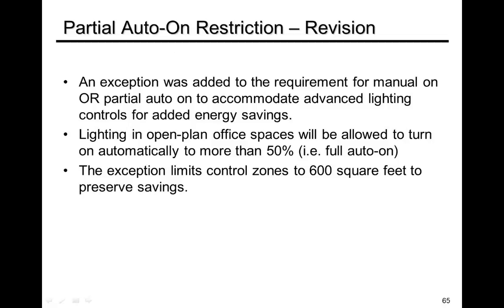The issue has been in open office spaces. There's always been a requirement for either manual on or partial auto on. And for most smaller spaces, this works well, but in the open office plan where it's been tough to save energy because of people going in and out at different times, there have now been developed a lot of advanced control systems that work very well, save a lot of energy, but they don't work well with a partial auto on or a manual on requirement.